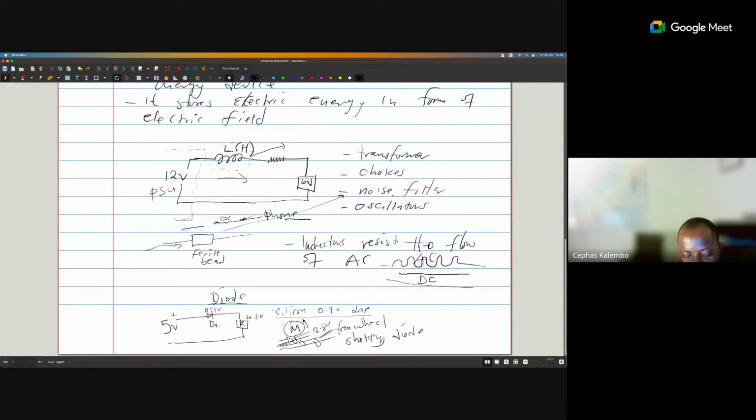You did not drive it just using transistors alone, because when that motor comes to a stop, you need to be able to dissipate the energy that it came to a stop with, that residue energy. So if you buy a motor driver, or just Google a motor driver, say an Arduino motor driver, you'd find that there are some diodes sitting there. Four of them, for the most part. If that motor driver is a 2-channel, you'll have 4 of them sitting there.